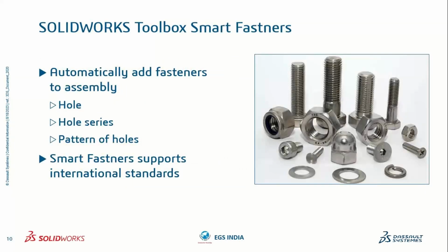And then the smart fasteners. Why do we need to go to smart fasteners? We already have a SolidWorks Toolbox library. If you're using the normal SolidWorks Toolbox library, we just need to drag and drop into our n number of holes.